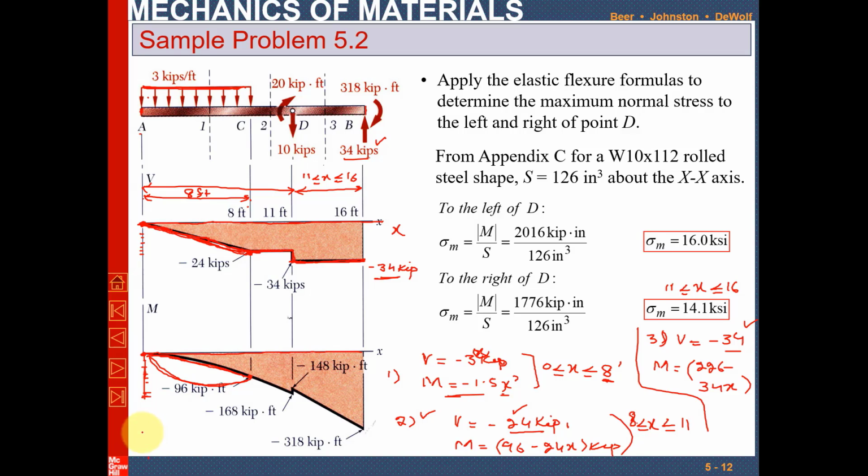Remember that if the shear force is a linear equation or a linear line, and it is going downward, or the slope is going downward, then the moment will be taken as clockwise. So you can join point 1 and point 2 in clockwise direction.